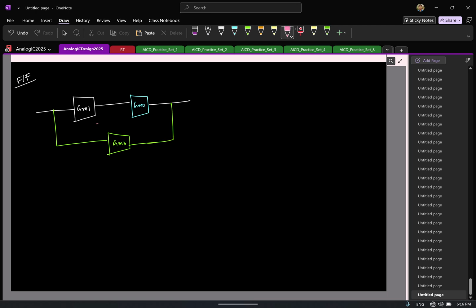Again, the idea is if you just have these two, the 2-stage structure, we have parasitic capacitors due to both of them, and we'll have a lot of delay. Now, when you introduce this path, it bypasses the parasitic capacitor here, so you get a faster response. That way you counter the delay in the feedback loop. That's the idea. Now we can do the same thing. To get a 3-stage feed-forward OTA, all I'll do is replace this second stage by another 2-stage feed-forward OTA.